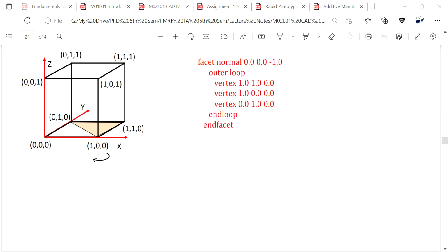So here the major thing you have to remember is, just beneath one triangle there will always be two triangles corresponding to one triangle on the top, and these two triangles will have 0 degree angle between them. But the adjacent one will never have a 0 degree angle between them. This will always have a different facet angle with the facet normal. So facet normal of this triangle will be represented by a line connecting the center of the above triangle.